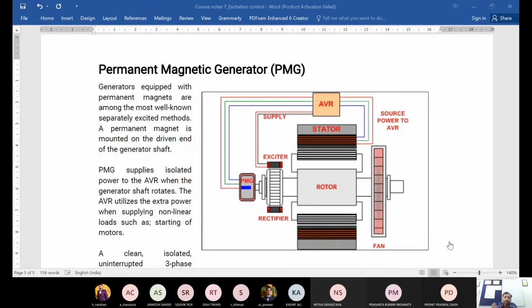Reactive power has a very close relationship with the voltage in the system. If there is a reactive power demand and it is not supplied adequately, then as the unmet reactive power keeps increasing, the voltage keeps dropping. In fact, it takes the shape of a nose curve.